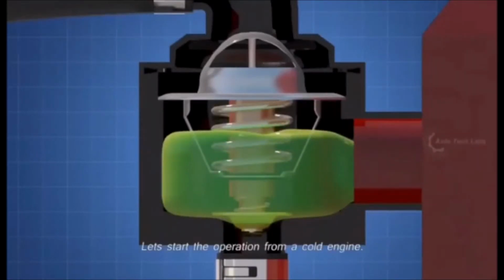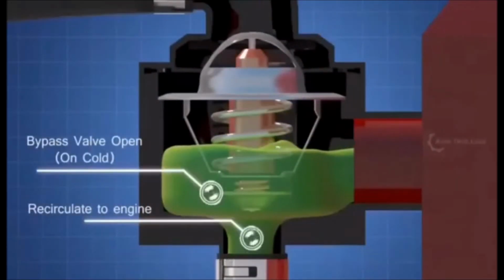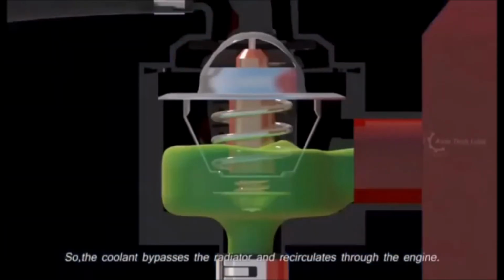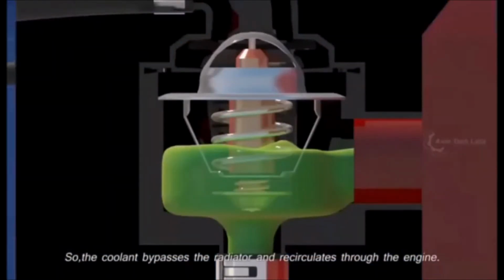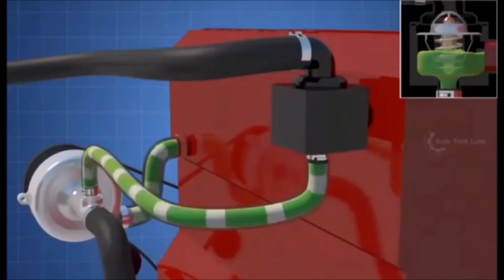Let's start the operation from a cold engine. When the engine is cold, the bypass valve stays open. So, the coolant bypasses the radiator and recirculates through the engine. This helps the engine to heat up to operating temperature quickly.